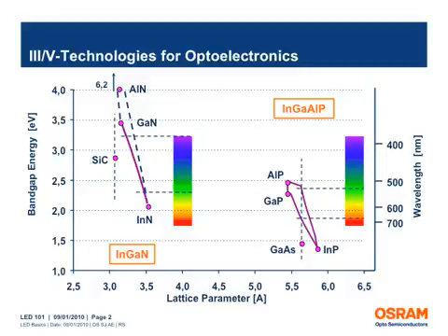This graph shows the bandgap energies and corresponding wavelengths for two major semiconductor materials used for LEDs today. InGaN, or indium gallium nitride, is used for violet, blue and green LEDs, whereas InGaAlP, or indium gallium aluminum phosphide, is used for green, yellow, orange and red LEDs.